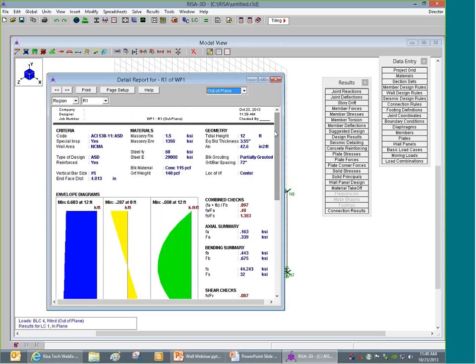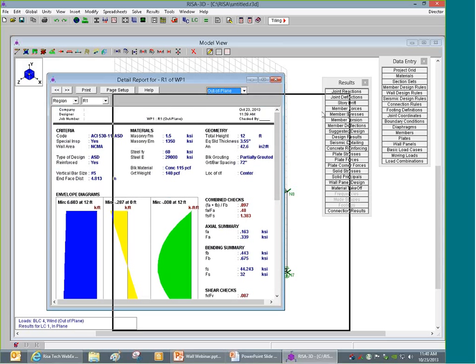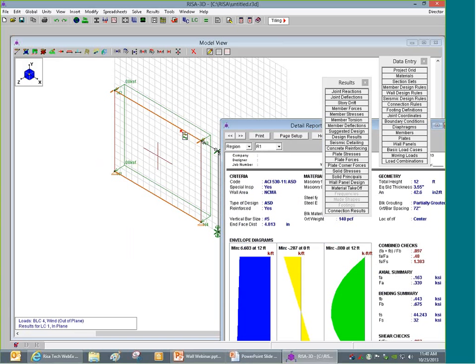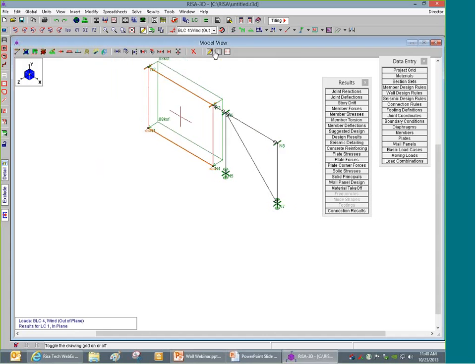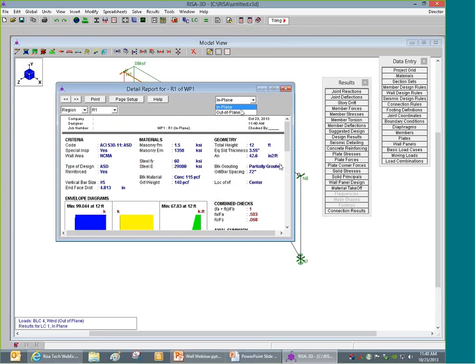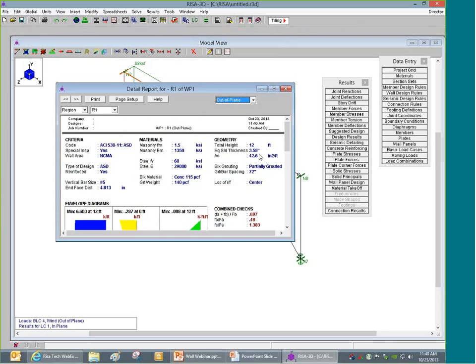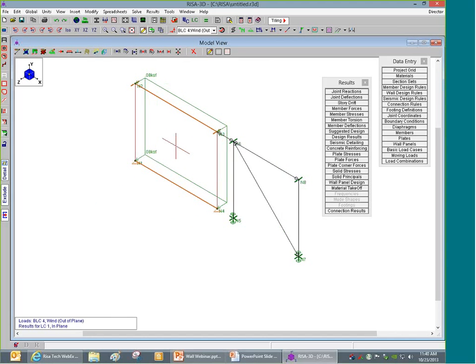Well, this is very important because this affects the stiffness of the wall. When we go in and we do that finite element analysis of this wall, we're considering a bunch of individual plate elements within the wall. And so we're calling these plate elements 3.55 inches thick in order to give us our deflection that we're going to get out of the model. And that deflection not only affects, of course, just what the deflection is, but it affects how other things are treated in the model.